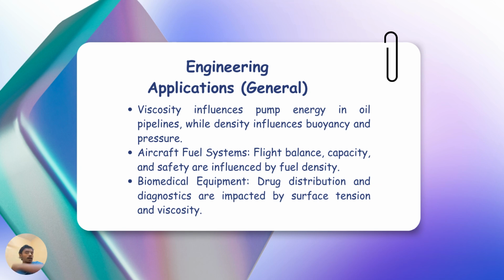Engineering applications in general. Let's look at how these properties apply in engineering. In oil pipelines, high viscosity increases the energy needed for pumping. In aviation, fuel density affects weight distribution and balance during flight. In biomedical devices, both surface tension and viscosity influence how drugs are delivered and how blood or samples move through small channels. Each property plays a critical role depending on the system design.